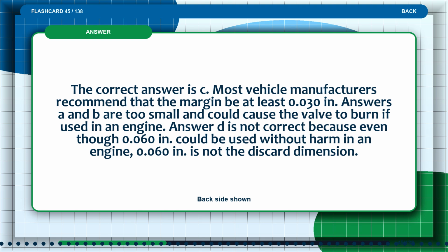The correct answer is C. Most vehicle manufacturers recommend that the margin be at least 0.03 inches. Answers A and B are too small and could cause the valve to burn if used in an engine. Answer D is not correct because even though 0.06 inches could be used without harm in an engine, 0.06 inches is not the discard dimension.